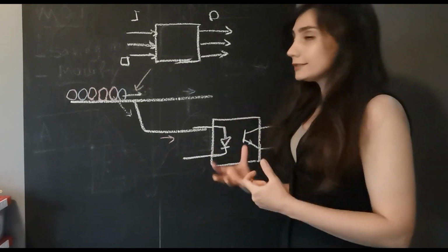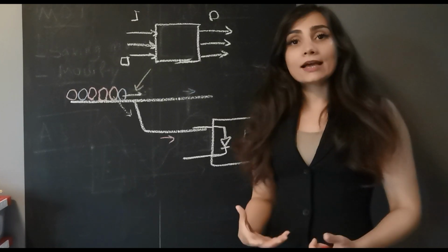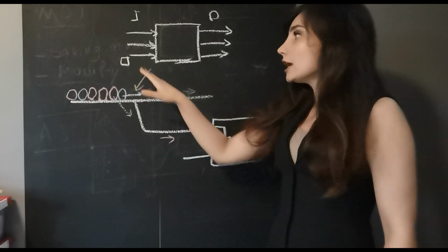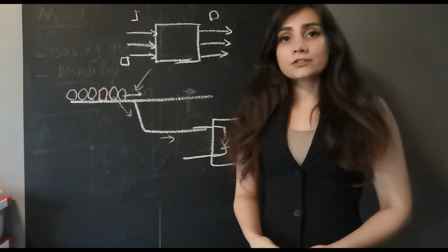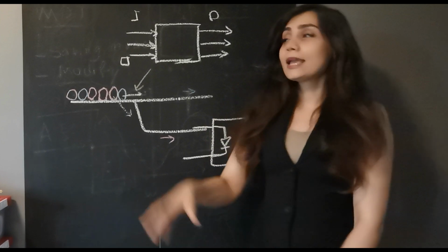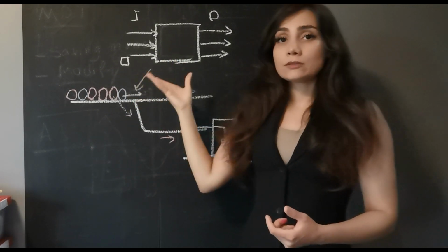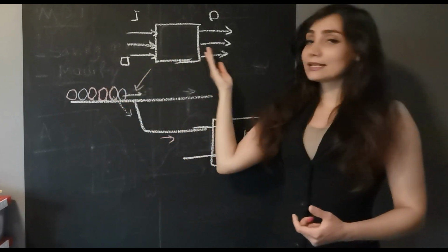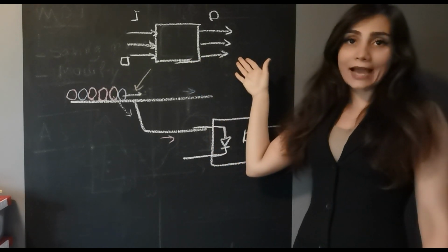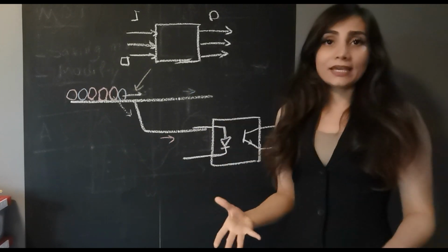To recap, a PLC is a controller unit, and it is used in industries because it can withstand harsh environments. Some of the most important parts of it are inputs, the sensors, and the switches. All of these inputs gather information about the environment. There's all of these instructions or the program. And based on the instructions that it has, it will make decisions and send a signal to the output. So these gather information and these do the actions. The outputs can be an alarm, it can be a motor, it can be any type of actuator.